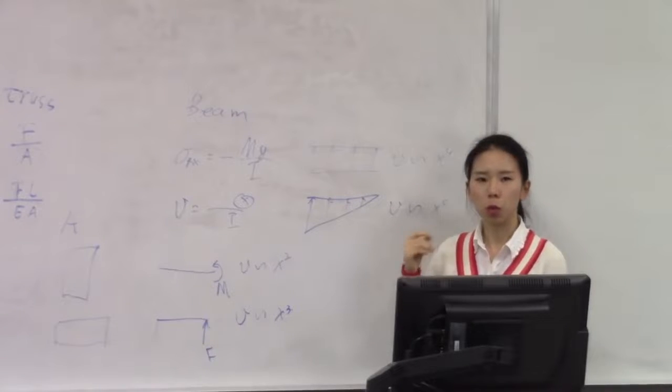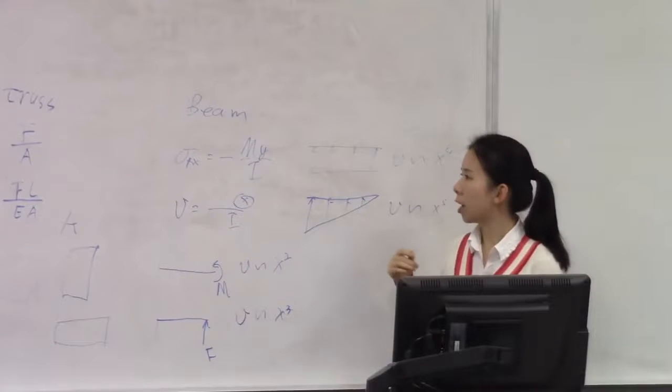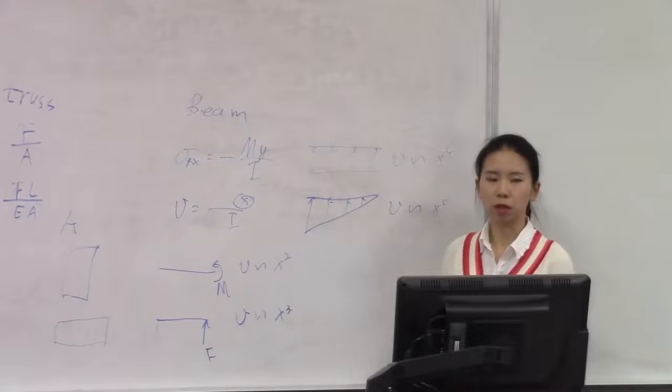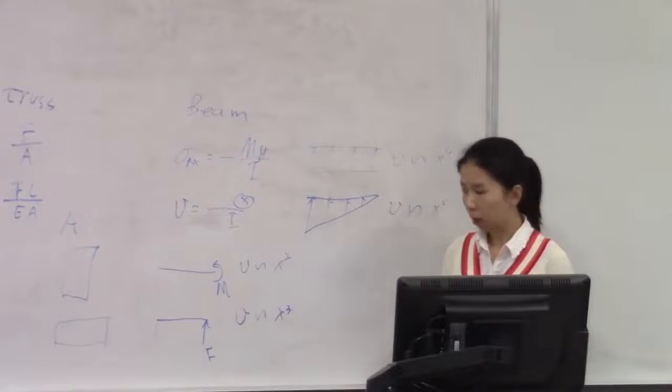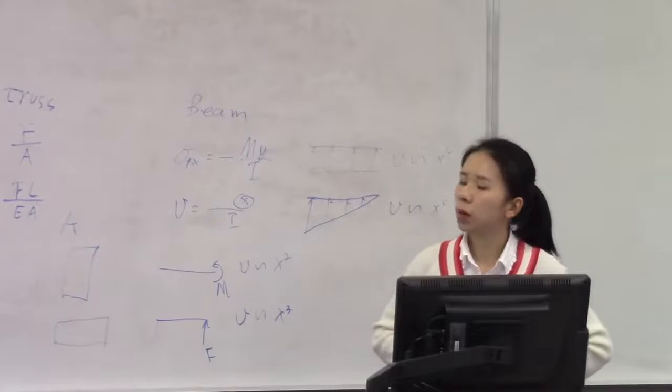you should use more elements. And the situation here is that the more elements you use, the more accurate result you will have, because it can only approximate. So this is the difference here. And so we will see that later.